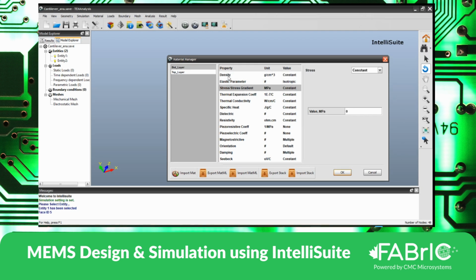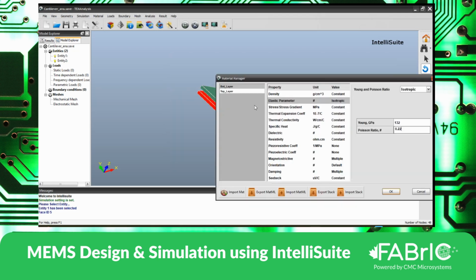How about the material properties? If I want to change these, then I can always change them. In some literature, we have 0.22 as the Poisson's ratio, and some may not have it. So based on the material properties that you want to change, you can always change them. Okay, so this is the bottom layer, and it's done. Now I have the top layer.